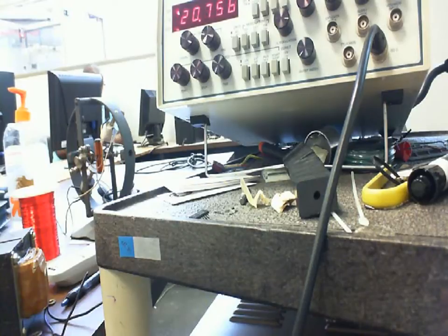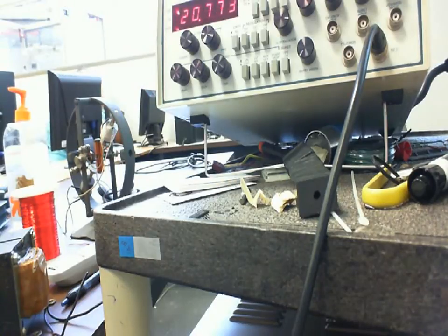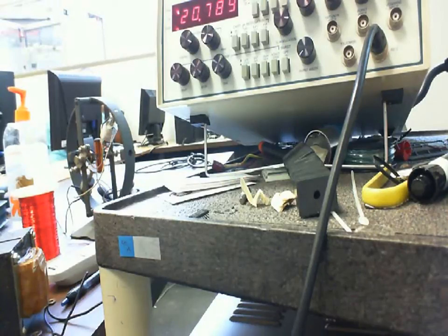And what we do, we add more teeth, we add more stripes, right? You understand? So if I put 2 stripes on each side, then I could count for 30 seconds, and it would still show me the same speed. If I put 3 stripes, then we could count 1/3 of the time, and then we would still get the same speed. So what we're doing is we're putting more pulses per count.